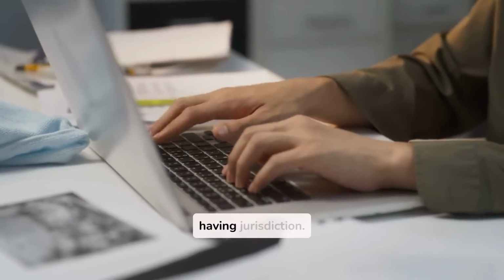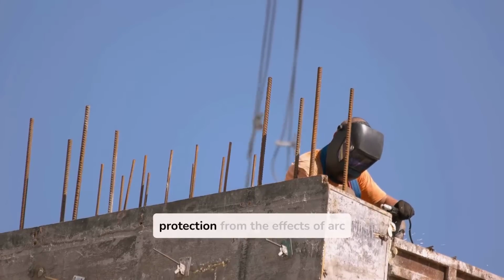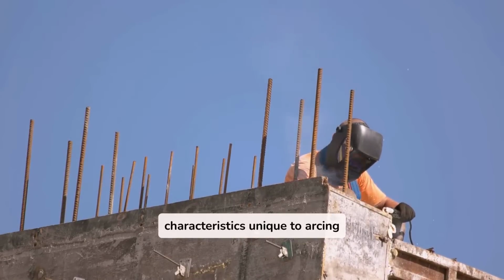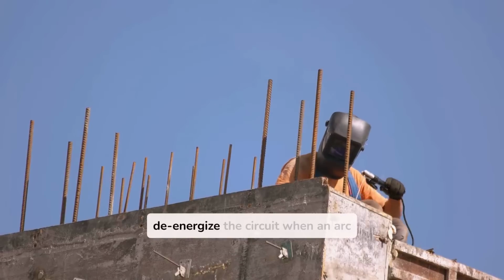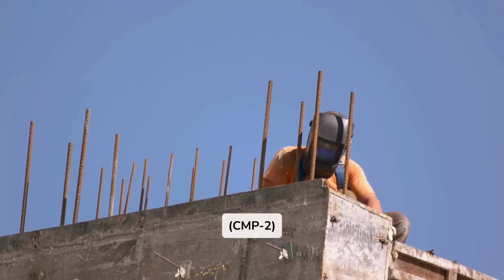Acceptable to the authority having jurisdiction, CMP1. Arc Fault Circuit Interrupter, AFCI. A device intended to provide protection from the effects of arc faults by recognizing characteristics unique to arcing and by functioning to de-energize the circuit when an arc fault is detected, CMP2.